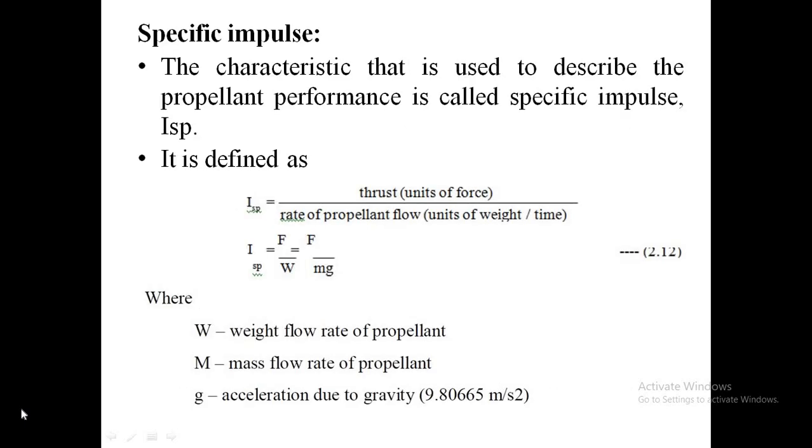Specific impulse. This is the characteristic that is used to describe the propellant performance, and it is defined as the ratio between the thrust in terms of units of force to the rate of propellant flow in terms of units of weight per time.